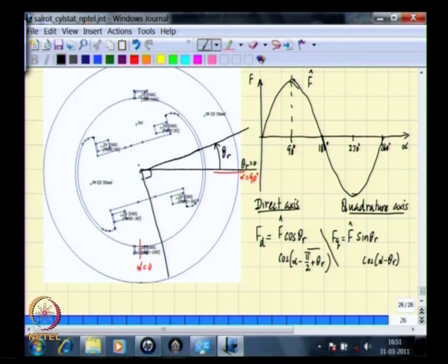So, this expression describes the original stator MMF resolved into a component along the direct axis and distributed sinusoidally around the inner circumference of the stator.